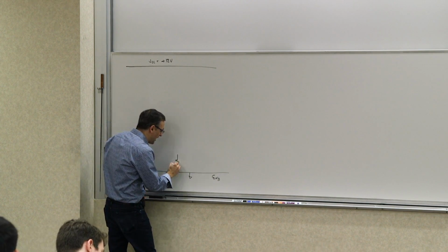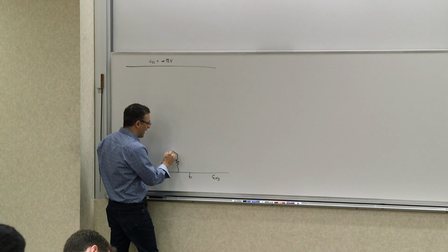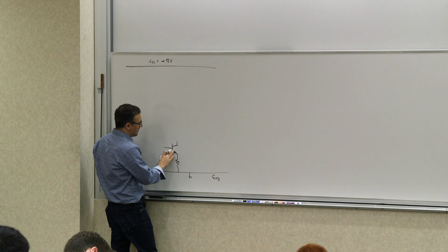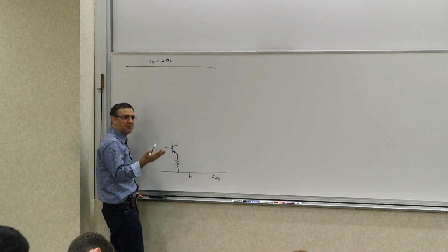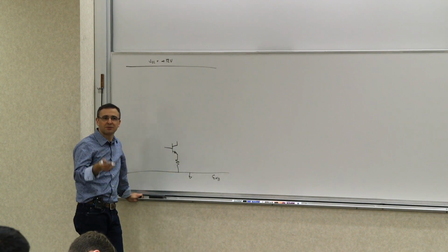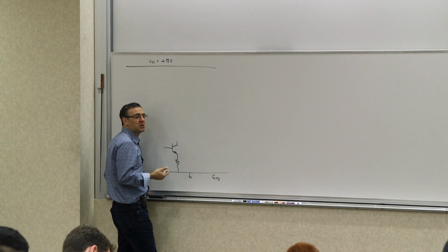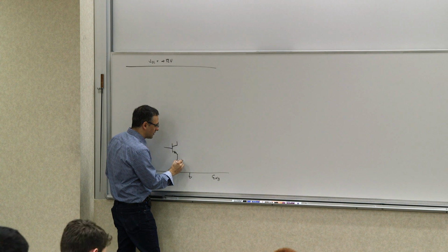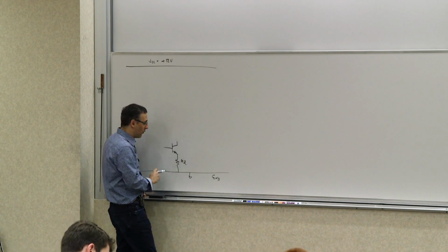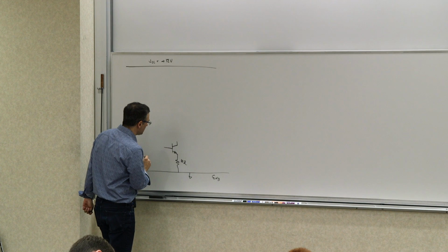So let's say you put a resistor in the emitter, and then you connect your transistor here. Now, Rm, let's say we said 1 milliamp before. I think we talked about 1 milliamp, just typical. I mean, it doesn't matter. 1 milliamp is 25 ohms. So I make this 1 kilo ohm, a 1 kilo ohm resistor here.